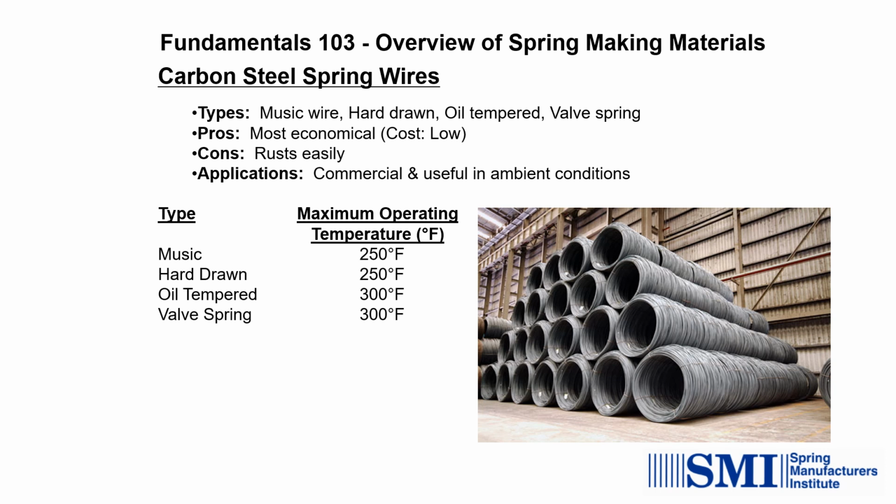Note the max operating temperatures. Music wire 250 degrees, hard drawn 250 degrees, oil tempered 300 degrees, and valve spring 300 degrees.